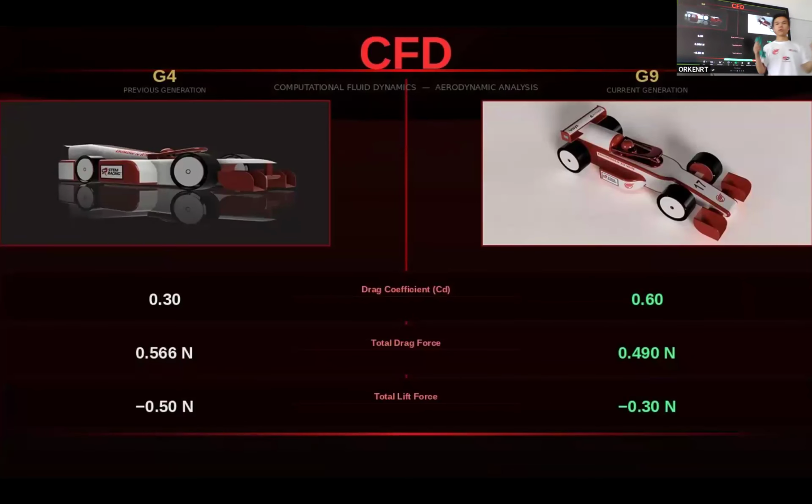After the first national round, our car was reaching around 2 seconds on the 20 meters of track. At that moment, we made a clear promise to ourselves. We had to cut at least half a second and reach the 1.5 seconds range. However, the final result went beyond that target. Through design, regulation checking, wheel analysis, manufacturing considerations, and a complete change in aerodynamic philosophy, G9 Prime achieved a predicted race time of 1.12 seconds. For us, this proves that abandoning the old concept was measurable engineering progress.